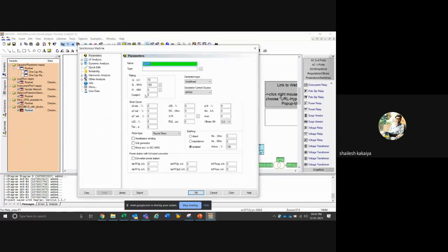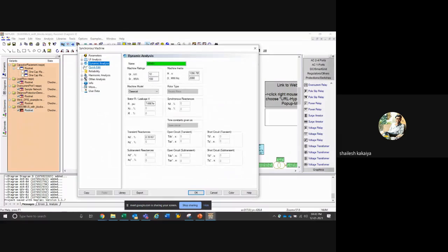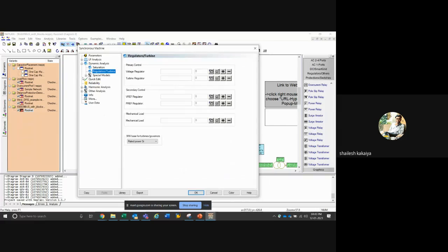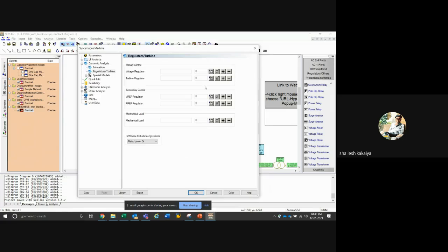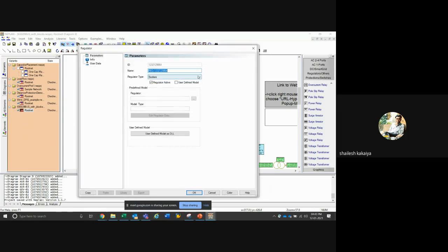I'll just show you a glimpse of that. NEPLAN has inbuilt exciters, power system stabilizers, under excitation limiters, HVDC master slave controllers, and VSC controllers. So different types of regulators are inbuilt, whichever are defined or available in the standards. For example, let me take power system stabilizers.